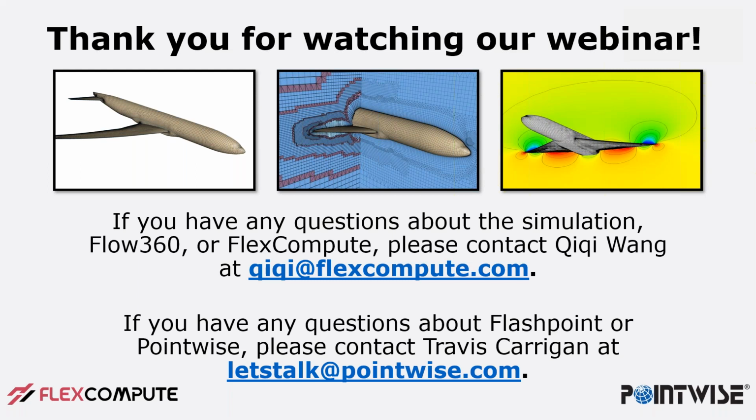So before Flashpoint, surface meshing was available. When we were doing this totally by hand, originally the process would take on the order of a couple of hours. For something like the CRM, it probably wouldn't take that long, but for most aircraft, it'd maybe take a couple of hours to get a mesh out the back end. Now, over time, we've started implementing some more top-down approaches like synchronized spacings, like automatically applying 2D T-Rex by just picking a connector and saying go. These things dramatically reduce that time. So where it may have taken a couple hours before, it was taking on the order of maybe half an hour to an hour, right? For a more complex aircraft geometry.